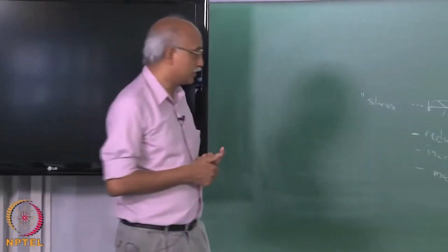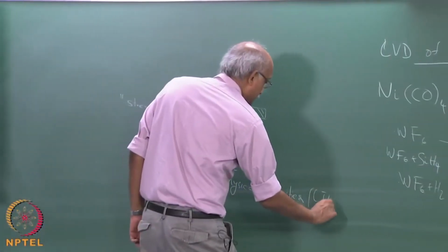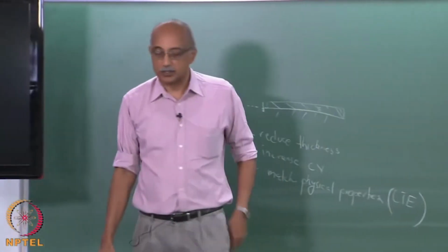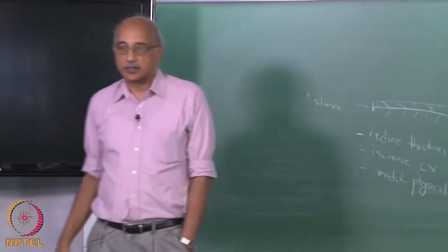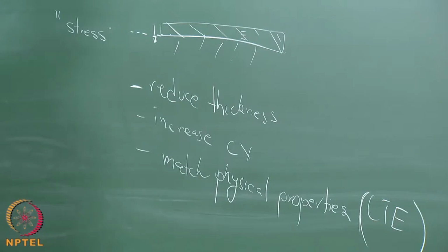So one of the most important parameters to try and match is CTE, coefficient of thermal expansion, particularly when the coatings are being used for high temperature environments.